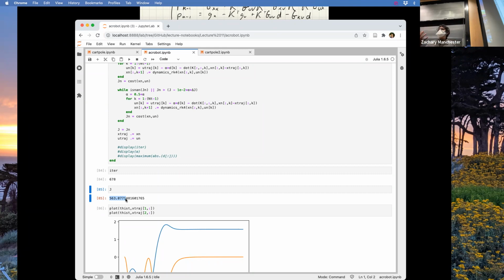I just made up that quadratic cost function, right? It doesn't matter if I hit that optimum or not. All I care about is obeying the dynamics, not violating constraints like torque limits, and getting to where I want it to go. Do I really care if it looks like this or the first one I found? Practically, probably not. So in a lot of cases, you just don't care, and just finding a local optimal solution is good enough for most applications.